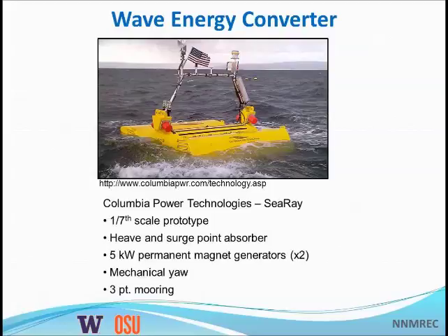So as mentioned, I'm going to be discussing noise from a 1/7 scale prototype wave energy converter. This device itself is a Columbia Power Technologies C-Ray. It's a heave and surge point absorber. It consists of two 5 kilowatt permanent magnet generators. It's got a mechanical yawing system and is held to the seabed using a 3-point mooring.